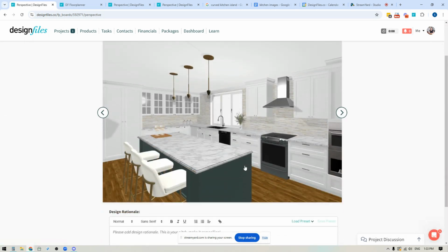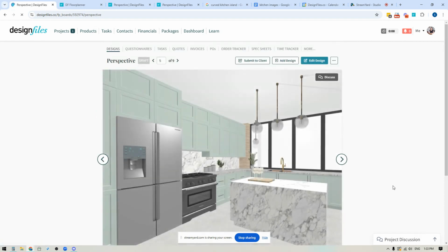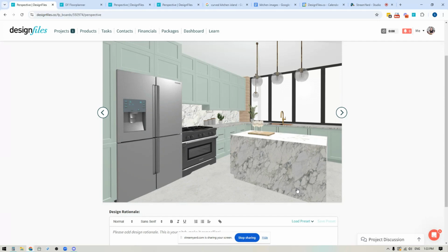You can also create your kitchen islands by just using the base kitchen cabinets and extending the countertop out the back so you have a sitting space. And you can also create kitchen islands just using the object builder, where you create your own objects and apply different finishes to them. So there are different ways you can go about it.